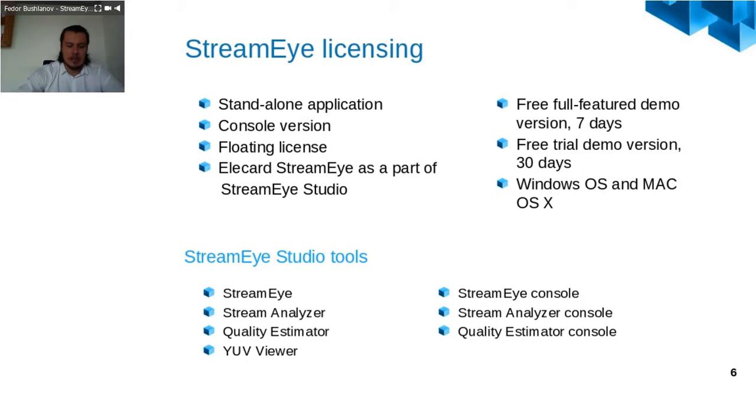That application allows you to analyze the transport stream level using the TR 101 290 protocol. That's a large document with explanations of different possible errors which may happen on the transport stream level during delivery of a video stream, commonly over IP networks.